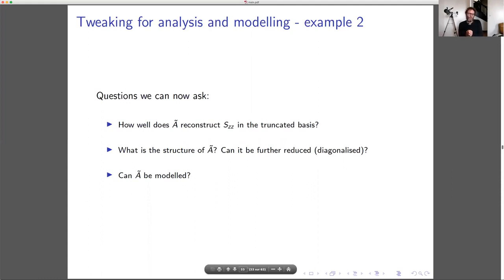If you're looking for a detailed understanding of the nonlinear interactions, it's best to use a molecular viscosity and leave the right-hand side as it is. Whether you use primitive or conservative shouldn't matter if you have full access to the right-hand side. You see what I mean? Mm-hmm. That makes sense.